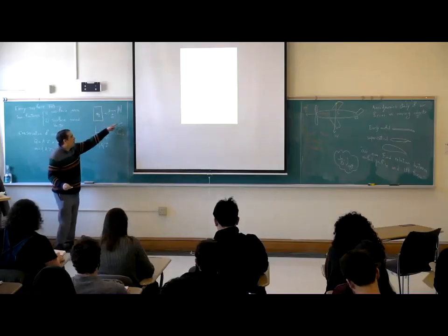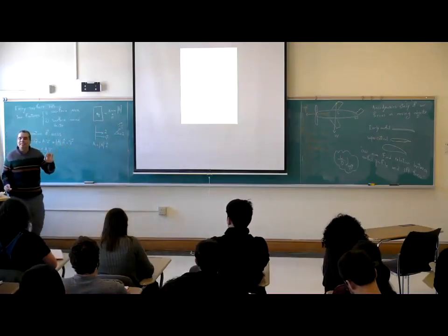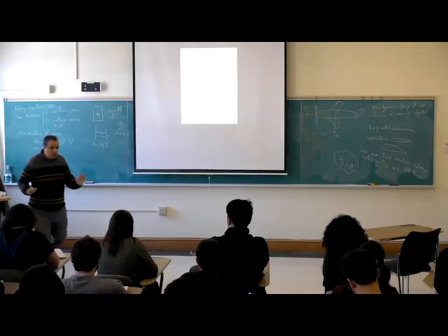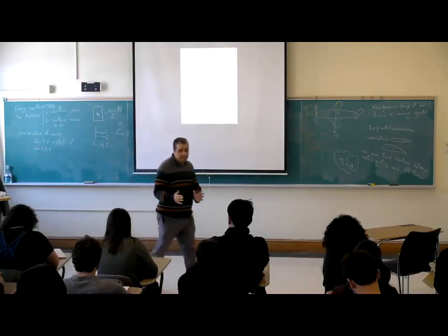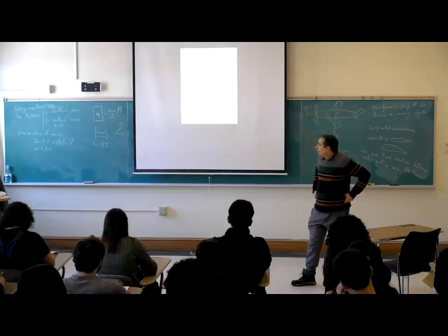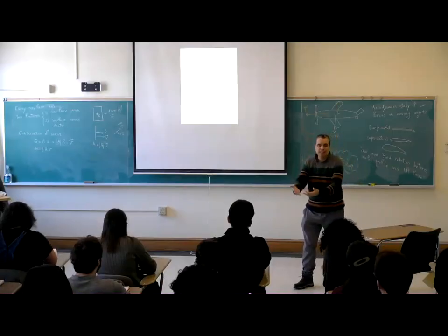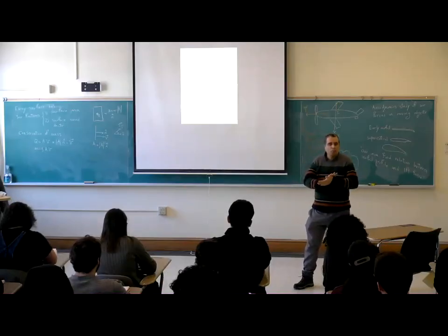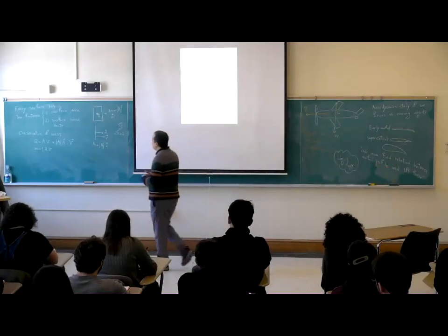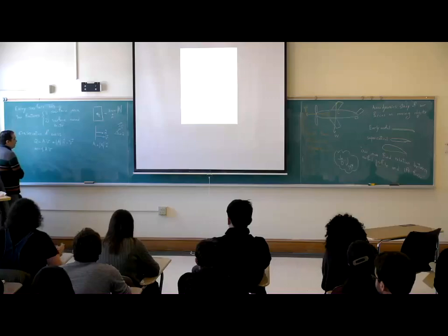So a component of v in the direction of n, because n dot v means projection, okay? Dot product means projection. If you project the velocity over the normal vector of the surface, and there is a component, there will be mass, there will be flow rate. Otherwise, there will be nothing, okay?